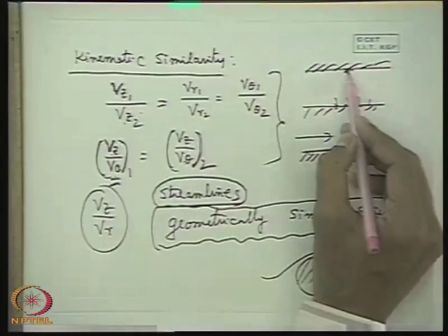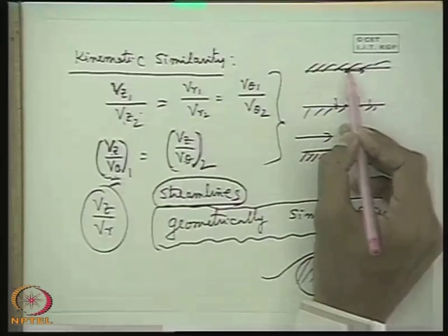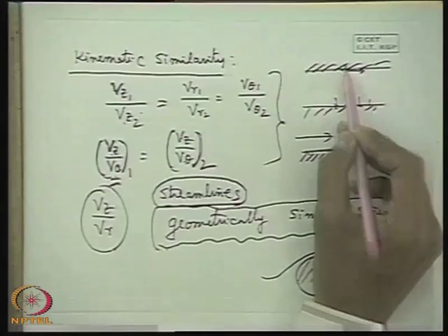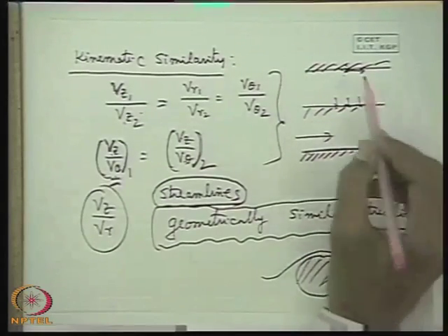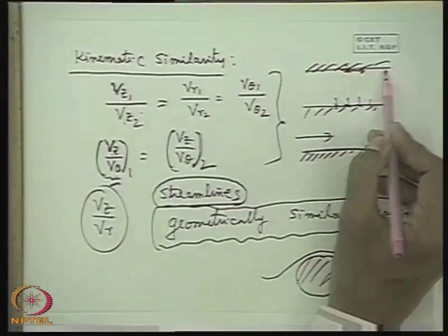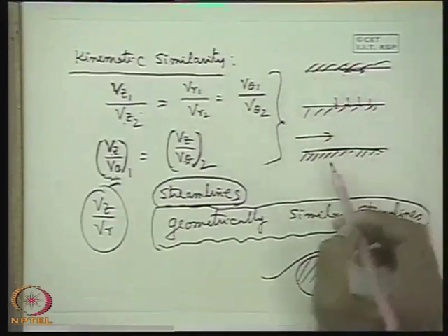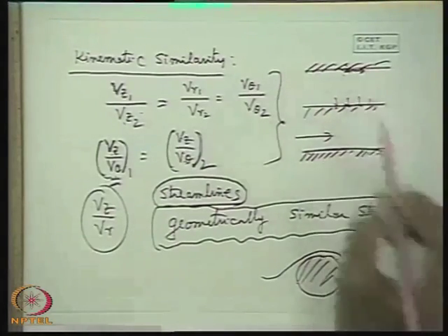So what velocity? This is the tangential velocity. That means along the solid. If solid is porous, the fluid will go into it. So the no slip condition is now a little modified: it is the tangential velocity, that is velocity along the solid surface, that is 0 for the fluid element relative to the solid. That means if the solid surface is at rest, there is no velocity.